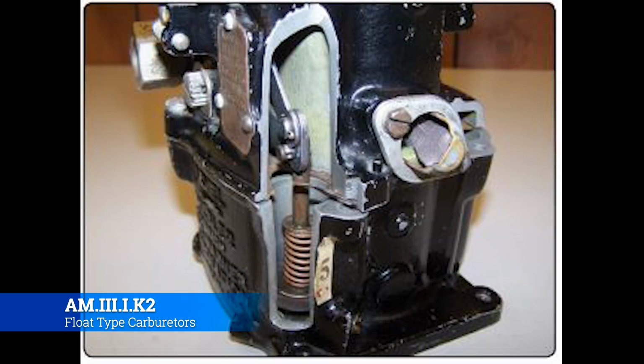Now, there's a few different types of additions that you can get into with carburetors. One of which is an accelerator pump. Now, an accelerator pump, basically what it will do is add just a little bit of extra fuel in case of a rapid, sudden opening of the throttle plate. Now, you could have a situation where you're flying along and you firewall it, and all of a sudden you need to go around, or something's happening that you need a lot of power all of a sudden, and the carburetor sputters because it can't catch up with the demand on it effectively. And so what the accelerator pump does, in the event that happens, is it basically just dumps fuel as much as it possibly can to allow for you to have that immediate power, and then allow the carburetor to go through its thing to catch up naturally, so that way it keeps on flying.